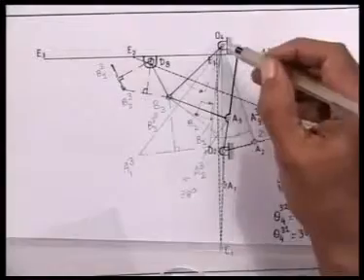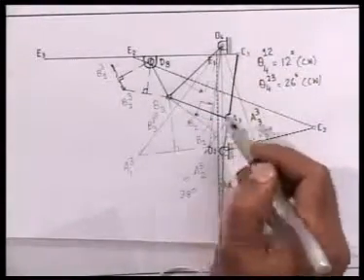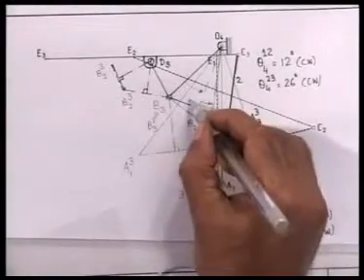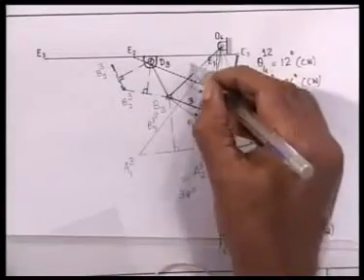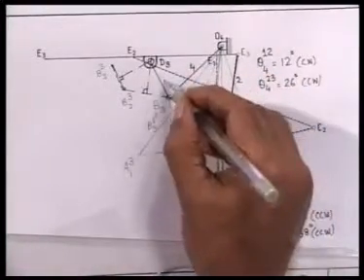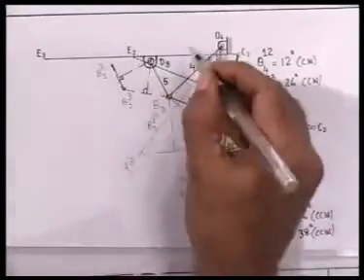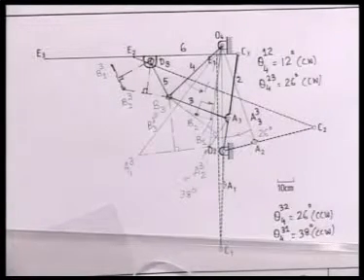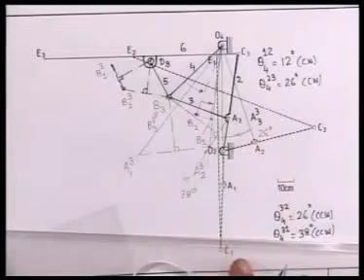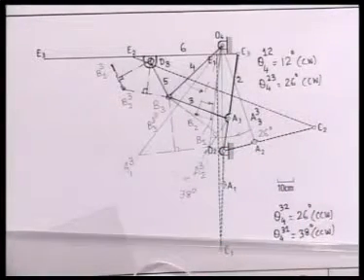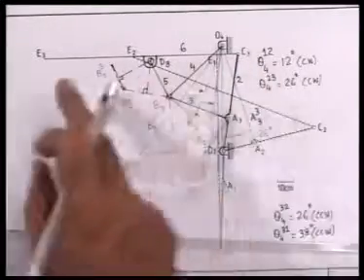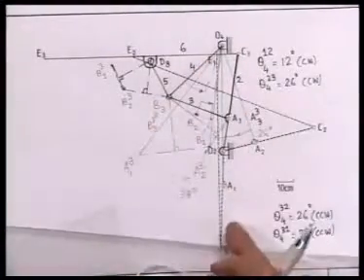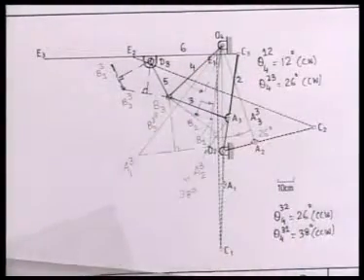O2, A3 is link number 2, A3, B3 is link number 3, O4, B3 is link number 4, B3 D3 is link number 5, and the door board C3 E3 is link number 6. So again we have used the multi-stage synthesis procedure to design the 6-link rail-less garage door mechanism, where the garage door has the desired movement, that is almost horizontal movement inside the garage, then drooping down fast to take up this vertical closed position.